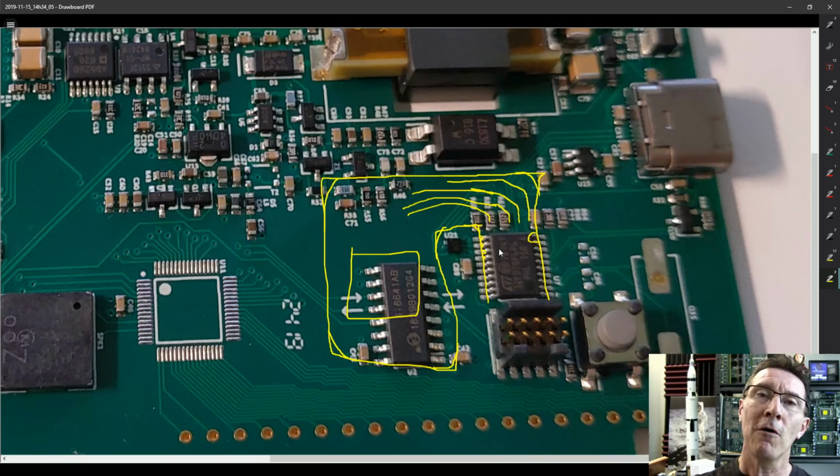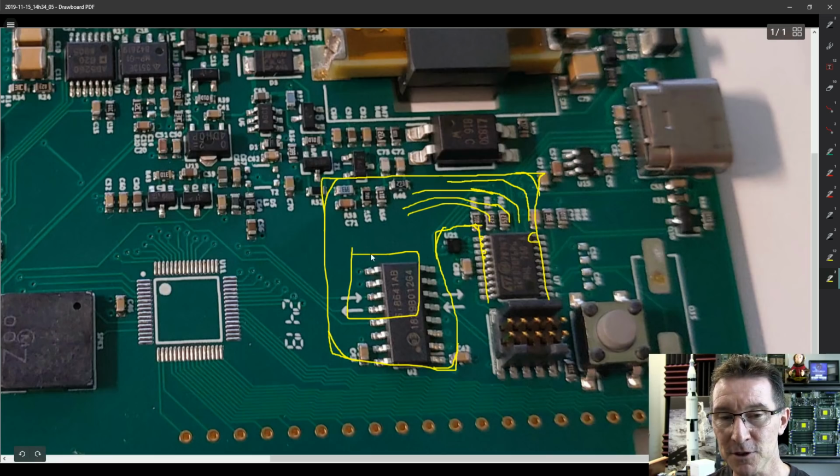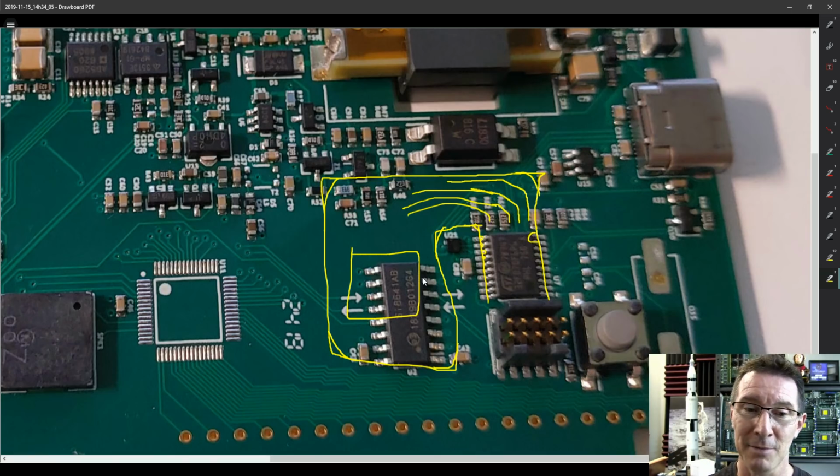So even though this board that we're doing for this particular application won't actually flex, so to speak, it'll just sit relatively flat like this on top of the existing chips and things like that. Just be careful if you've got exposed pads on the bottom, make sure they don't short out to the tops of any other components. So you'd have to put some sort of insulative layer on the back. You can have another layer of polyimide material stuck on the bottom of your board so that none of your vias are exposed. And of course you could do tented vias and stuff like that. But just be careful that nothing shorts out.